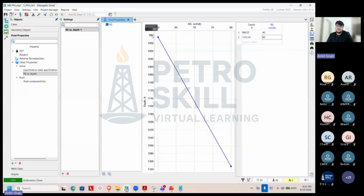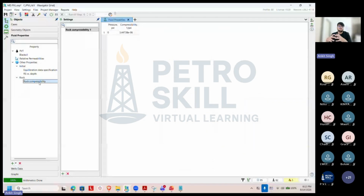So you see how my gas is evolving over the course of depth, right? So this is one. Then we have also the rock compressibility, like how much the rock is compressible. So we are going to define that as well. If you have compressibility data, you can just directly enter it, or you can create a default by grid, and it will automatically fill in. This option is not available in all the tools. I worked in some of the tools, but I haven't seen this kind of thing. In tNav, it is available.